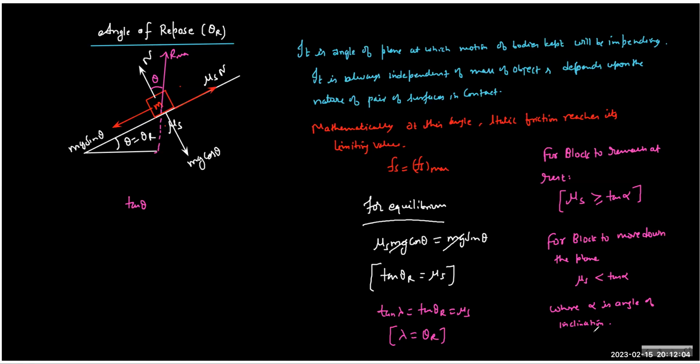So whenever you start pouring, if the slope exceeds the repose angle, the grain starts coming down. Okay. And they will always keep on coming down till the slope of the cone, the slant, if the slant is like an inclined plane, and if that inclination is less than the repose angle, it will be stable. The moment it crosses, it will start falling to the next layer. So it will change the slope actually, because you're pouring some material.